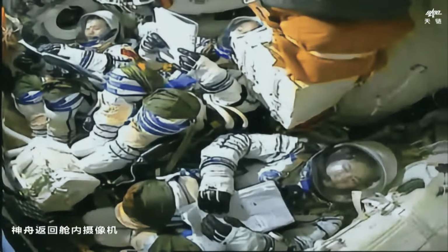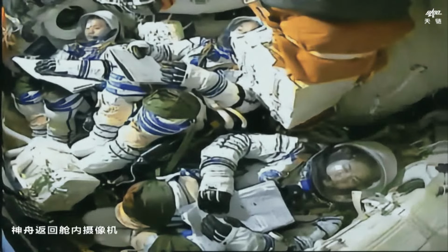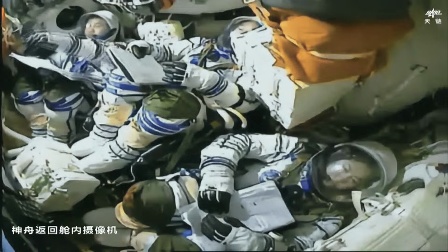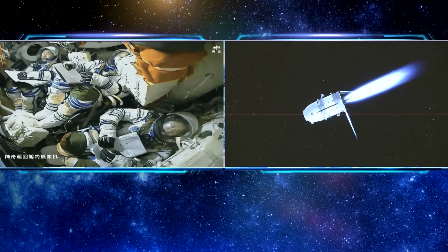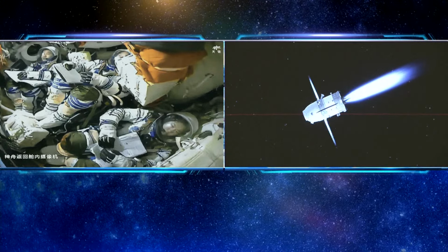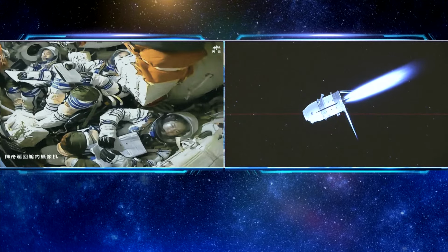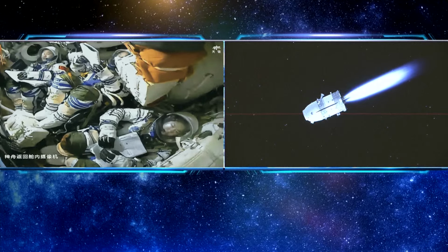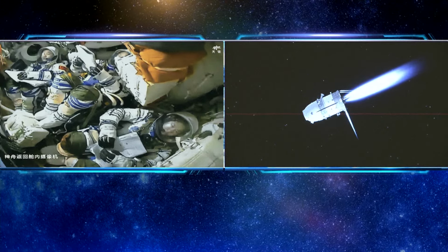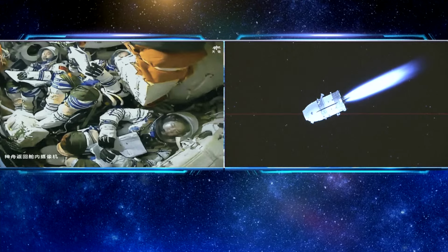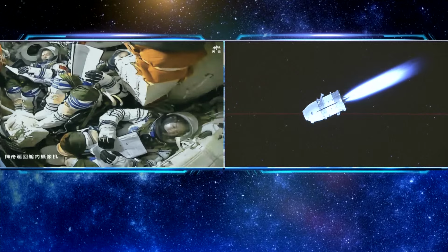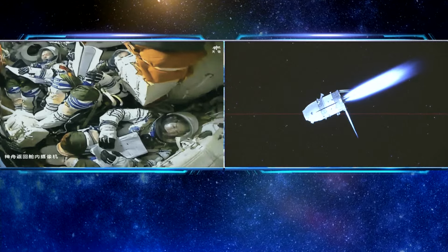As we just reported about 5 minutes ago, the capsule has finished at least 2 adjustments of its altitude. Why exactly is this so necessary? You know that our Shenzhou spaceship has a 3-module design. The first step is the separation of the orbital module, as your colleague already mentioned in the Beijing Flight Control Center. This is to reduce the total mass of the spaceship. But to avoid any collision, we must separate in a different direction. That is why we conduct the first attitude maneuver of about 90 degrees.